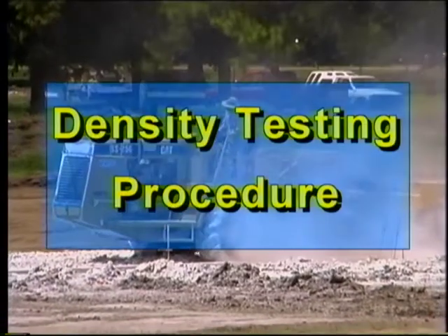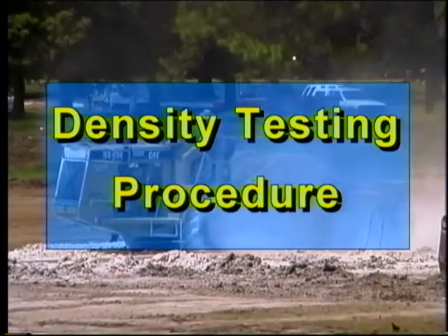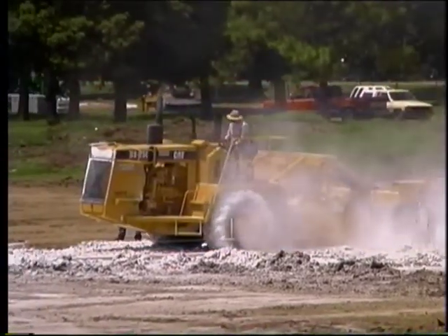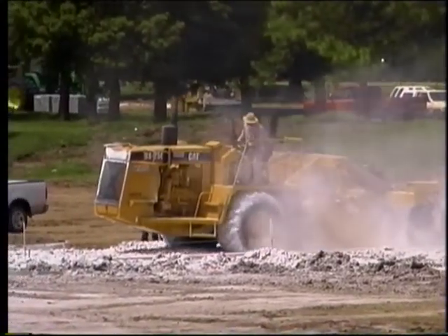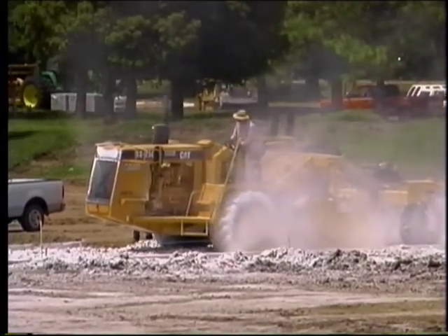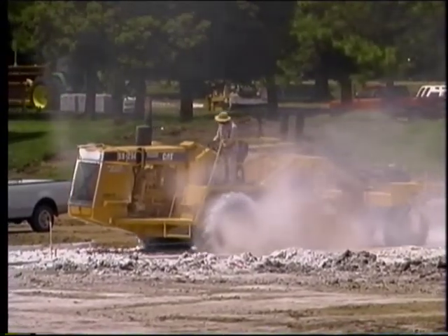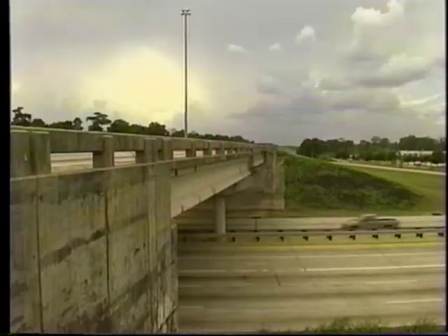The density testing procedure. Site location. Select a test location greater than 1.8 meters or 6 feet from any object that may interfere with the testing process and cause erroneous results.